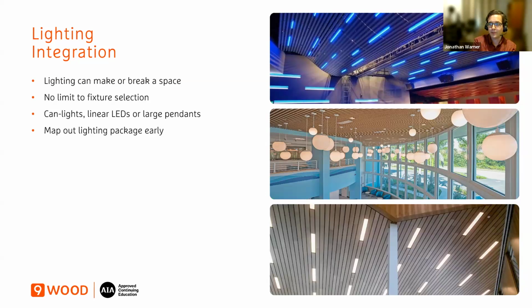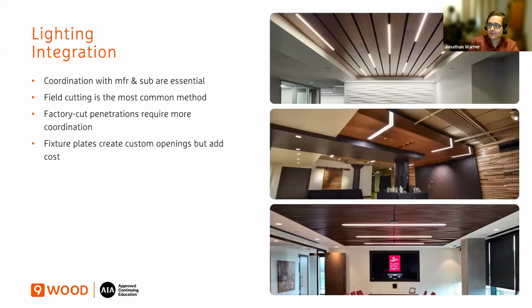They can break up the wood member, segment it, and it's important to map out lighting packages early and make sure the manufacturer has a plan for how you're going to suspend the weight. Is there enough room in the plenum? How's that going to impact accessibility? There's a long checklist of things to go through to make sure you don't end up with headaches later on, during the shop drawing or installation process. God forbid that work there.